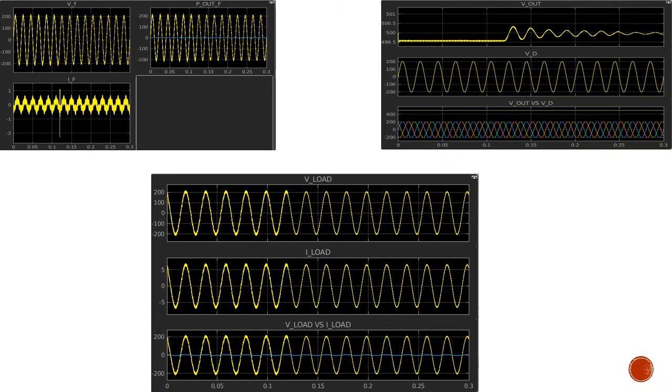On the simulation part, the output at point B is 158.27 watt. Even though it has some power at point B, it still has a very small current to flow throughout the inverter because the current will flow to the LCL filter as well. At point D, the output power is 2021.55 watt, which is almost 2 kilowatt.